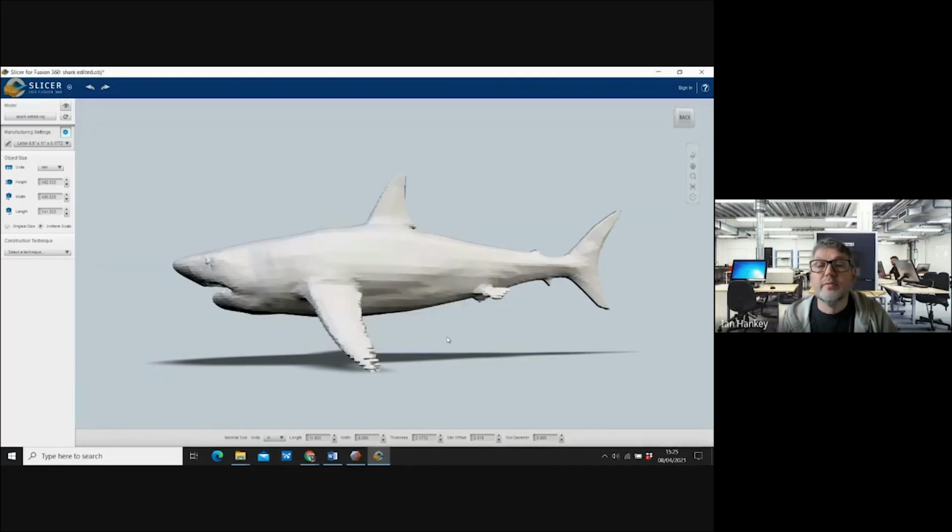Left click on done. So now when I go to the material settings, the manufacturing settings at the top here, where it says letter, we've got a drop down little arrow there. I'm going to left click on that. And if you slide it all the way down, at the very bottom here, we can see our plywood, 4mm by 500 by 375. I'm going to left click on that. And now we've selected that as our material that we're going to use.